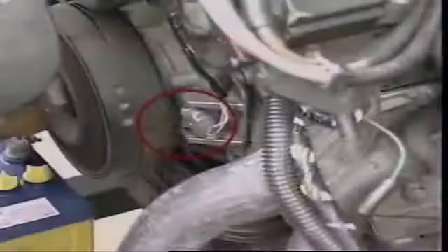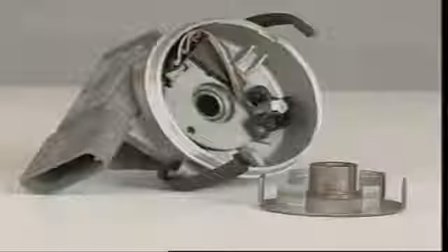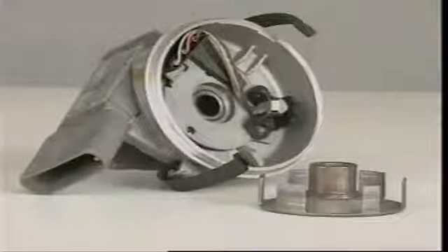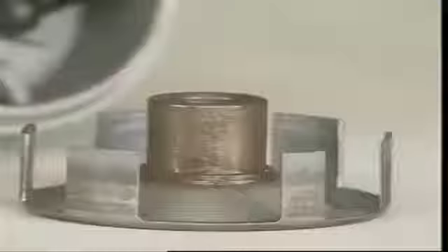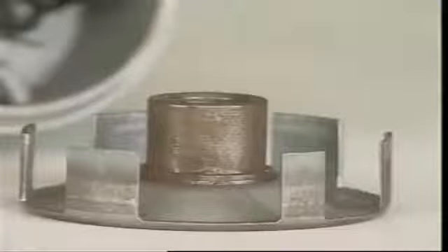Hall effect sensors can also provide a voltage signal and, like the inductive type, can be mounted on the crankcase wall or inside the housing of the distributor. The sensor has a permanent magnet and a Hall switch as part of its assembly and an air gap between the magnet's north and south poles. The switch is on one pole of the magnet and an interrupter ring with a number of square-shaped blades or segments rotates through the gap formed by the poles.